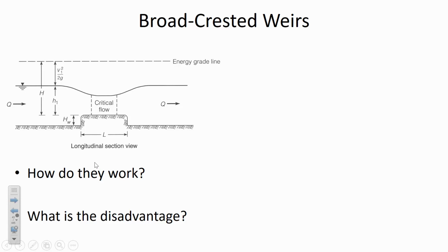And so we're talking about some channel where the bottom width is B, and of course the top width would also be B because it's rectangular. And we've got some flow rate going through the channel, and so we're trying to find out on a basis of each unit of width how much flow is going through there. So the critical depth, y sub c, is lowercase q squared divided by g to the 1/3 power.